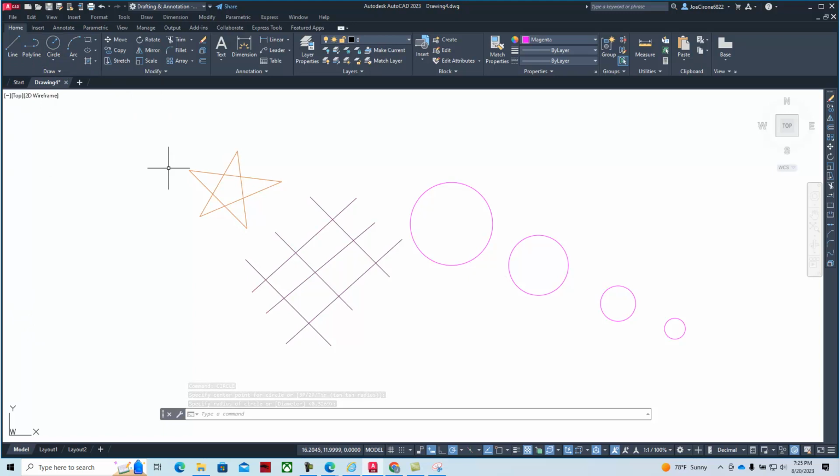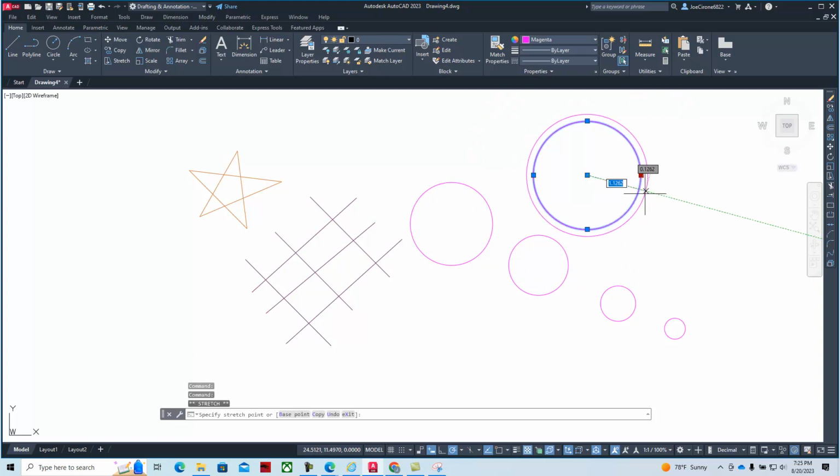It depends on the scale of the drawing, but when we create something like circle center radius, we can click where that circle is going to be, and then we can type in the radius. And so I could say 1, enter, and now if I analyze that, it's a 1-inch radius circle. And we can delete it.